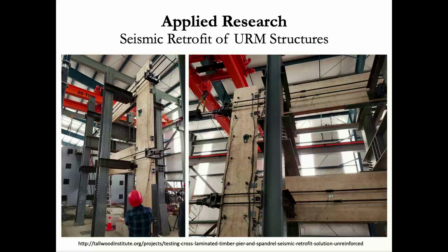This project is just an example of some of the stuff that's going on, where this was a seismic retrofit system that was conceived and designed for unreinforced masonry structures, with the thought that maybe you could design something out of mass timber that would be able to be rapidly deployed and assembled inside the URMs without causing excess disruption to people in the building, and cost effective, something that obviously could be done at reasonable cost. That work is still ongoing, but the results are quite promising.